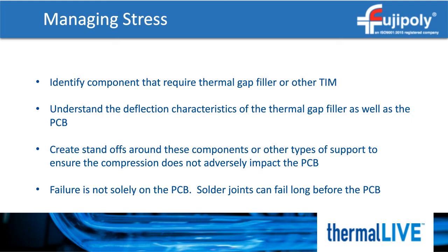When you have selected a pad, try to get a good understanding of the compression characteristics of the pad. At our engineering center, we do offer testing of pads at the specific size, boundary conditions, as well as the rate. This data is very helpful to understand the stress created during assembly and the stress over time.